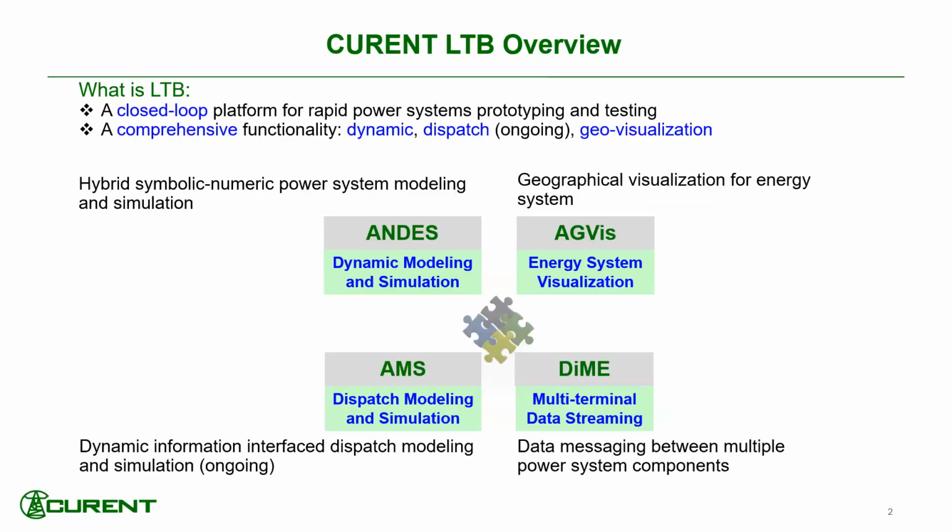So what is LTB? First, LTB is a closed-loop platform for rapid power system prototyping and testing. The closed loop here means your controllers are in the loop of the power grid. Your controller will take the signal from the power grid, and then the control signal will be fed back to the power grid.